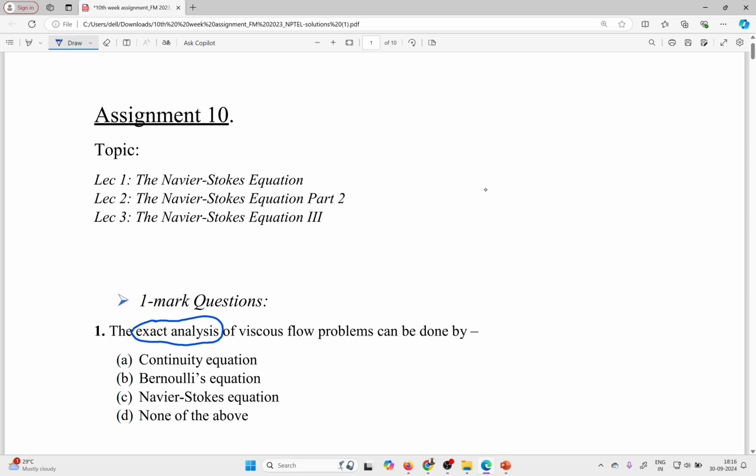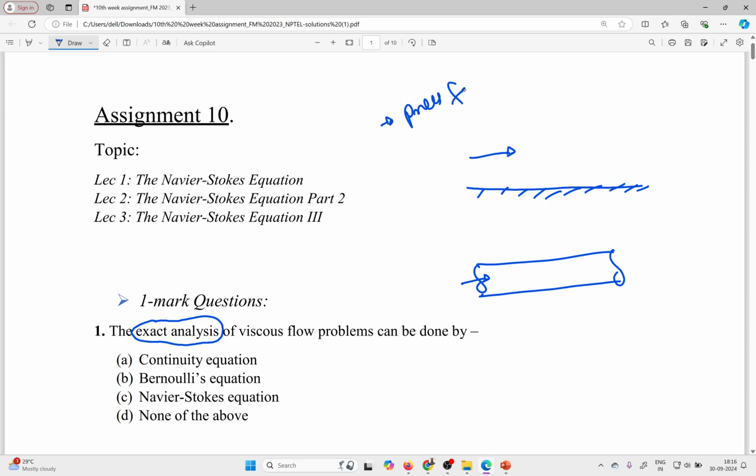let us suppose if water is flowing, if this is a channel or river you can say, or pipe, you can take the example of pipe also, pressure flow. So this flow having pressure force, another gravitational force, or you can say the body force, another shear force between the layers of the fluid particle due to the viscosity. You can say the viscous force also,